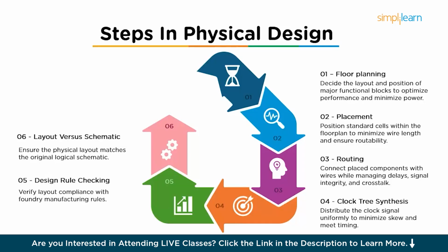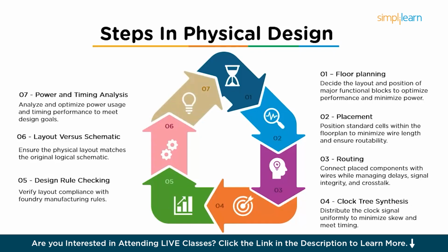This process, known as LVS, compares the logical representation of the design with the physical layout to ensure that no mistakes were made during the physical design phase. Then comes power and timing analysis. The power and timing analysis checks ensure that the chip meets performance goals like timing closure and power consumption. The designer uses static timing analysis (STA) tools to check for timing violations and optimize the design.